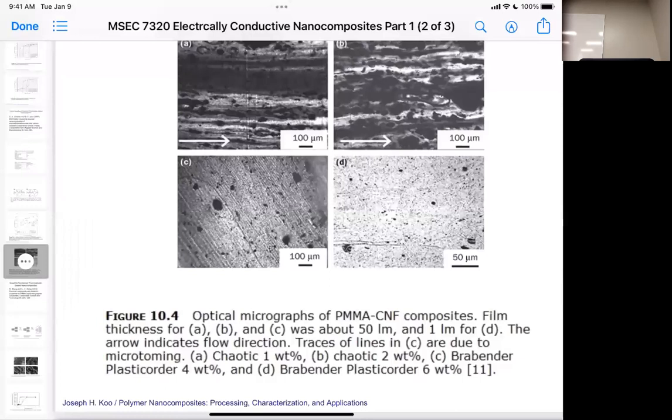In general, the better dispersed your system is, the better conductivity you have, because you have more of the conductive pathways possible. Because in the second one, you'll see they have a similar kind of arrangement in the opposite direction to the conduction, but I think maybe they have the holes that stop the conduction, the lower one, the third one, right? Yeah, so these are the ones that were done in the other one, the counter. Plates, yeah. So let's see, this looks well dispersed, but maybe these aren't close enough together at the lower loadings to get them to the percolation. There, it looks like the particles are aggregating in sheets, almost like ribbons. And that's giving them the higher conductivity.